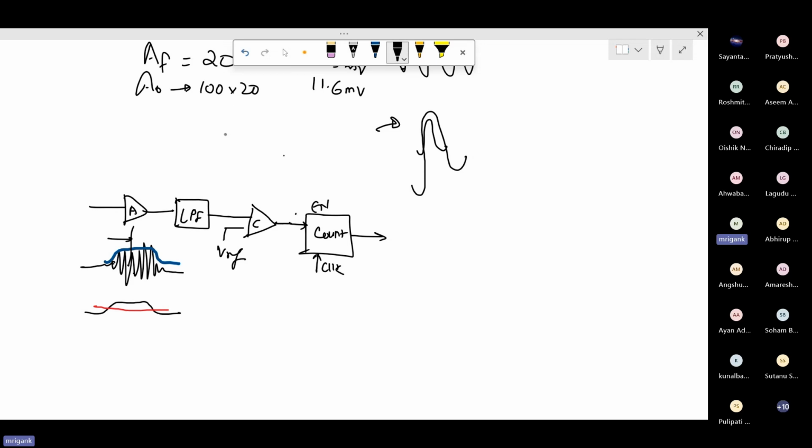So remember that on chip we cannot have very large resistors and capacitors. If you are using an op-amp based filter, to get that very large feedback RC value we have to use some special schemes, just like we discussed last time, the subthreshold resistor to get the very large R. The on-chip capacitor will be very limited, it may not go beyond a few picofarads. And for this R, you can use the subthreshold transistors.